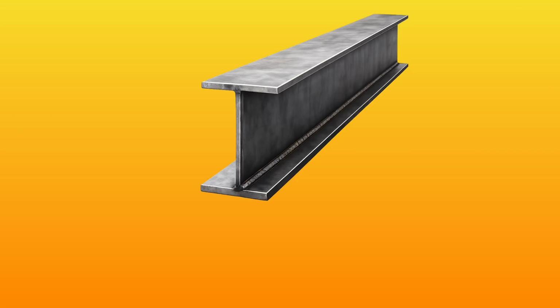Steel beams behave very differently, and they can carry some huge loads. The atoms are held together by a metallic bond, and it's this metallic bond which glues the whole lattice together. For an I-shaped beam taking vertical loads, the bulk of the shear is taken in the web. That is the tall, slender plate that's going vertically from the top flange to the bottom flange.